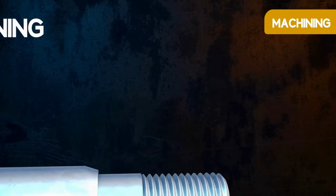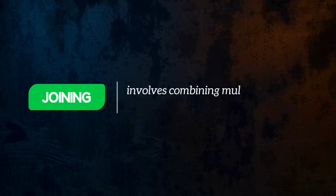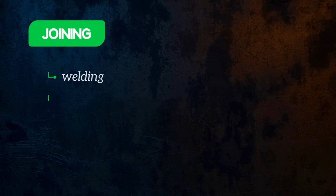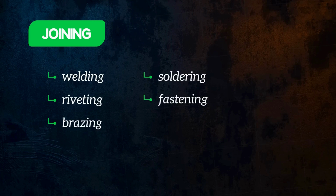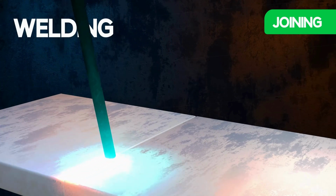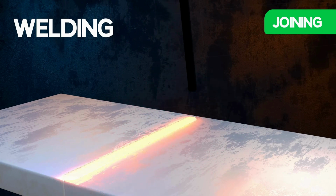Let's move on to the next category. Joining involves combining multiple separate components into a larger assembly. Like machining, joining is a secondary process. Welding, riveting, brazing, soldering, and fastening are all different types of joining processes. Welding uses extremely high heat to fuse distinct metal parts together. Unlike soldering and brazing, the base metal melts during welding.